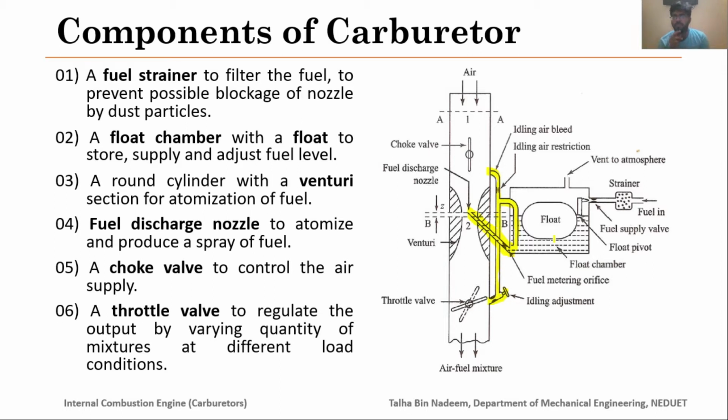In an idling condition, when your throttle valve is slightly open, a lesser amount of air enters from the air filter to the venturi section, and only a small amount of fuel enters from the float chamber into the venturi throat, because there is not much pressure difference, not much carburetor depression present here.